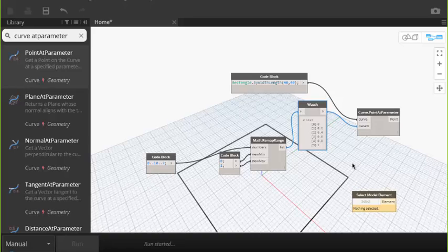What I also use it for is to distribute elements on lines picked from Revit. For example, if I want to distribute some windows in a facade, and these facades follow an A, B, C distribution, then I'm able to pick the insertion point of those families, and then use remap in order to place them in Revit.